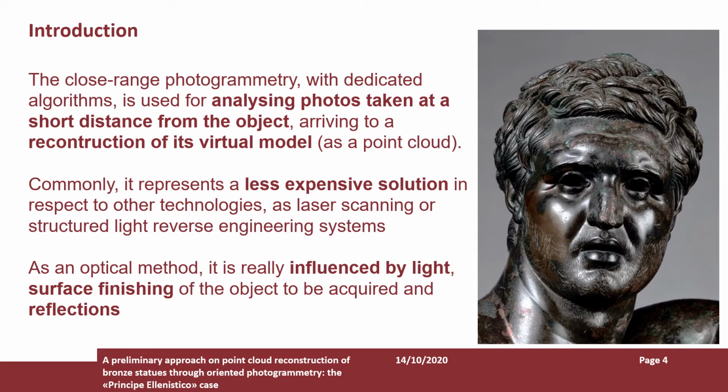Compared to other reverse engineering technologies such as laser scanning or structured light, close-range photogrammetry is generally cheaper and needs less specific tools. But obviously, being an optical method, it is highly influenced by light conditions, by the surface finishing and the material of the object, and by its possible reflections.